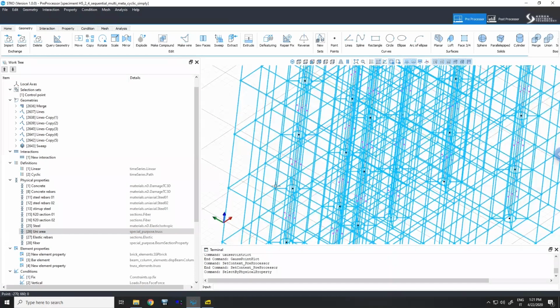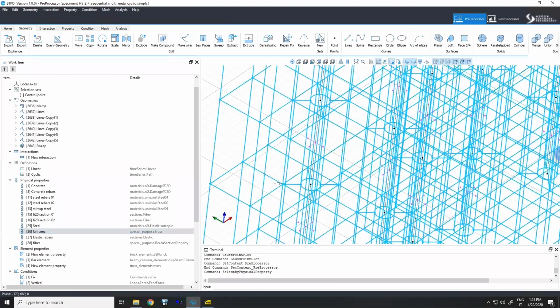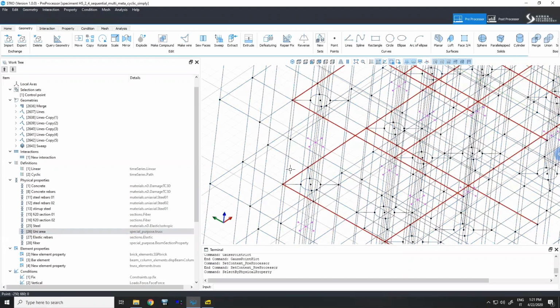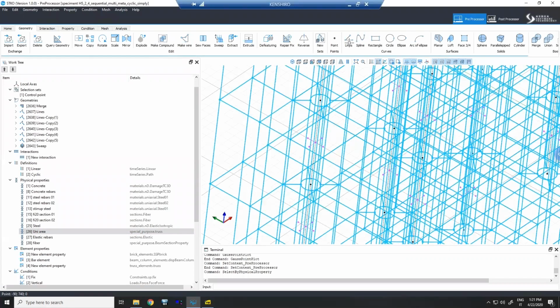Now, in case of a shell, you can do the same also for the beam because the shell has 6 degrees of freedom. So you can directly assign the beam section to the border of the solid, you don't need to create an interaction as we did in this example. So the note here was perfectly correct. In case of shell, as Miguel Pereira was asking, you can directly assign the beam property onto the shell edge. Basically, that is what we did, in fact, in the reinforced concrete shear wall example. I drew the shell and I assigned the lateral boundary beams directly on the edge of the shell. I didn't create an extra beam, in fact.